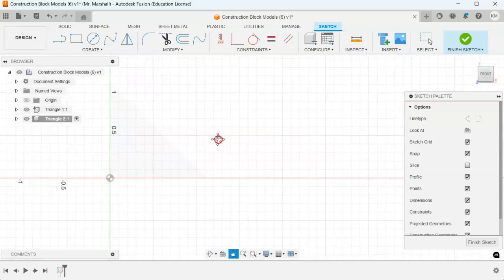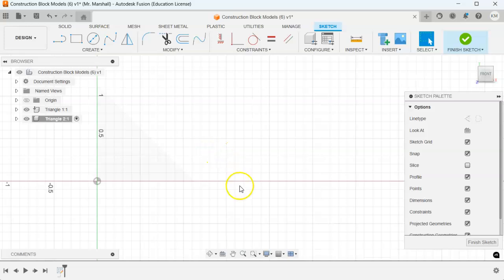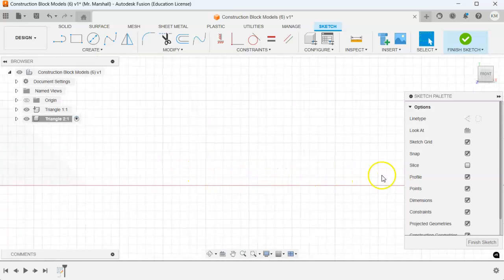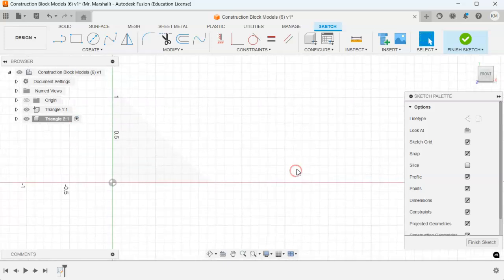Now it's going to be really nice using the sketch command rather than primitives to be able to line our objects up nicely so they're related well to each other. As long as I keep using this x-axis, I can start putting all of my objects along this x-axis, and it'll create a nice little matrix for us. So I started a sketch. I'm in the sketch now, in the sketch ribbon, and I'm going to do the same procedure as last time.